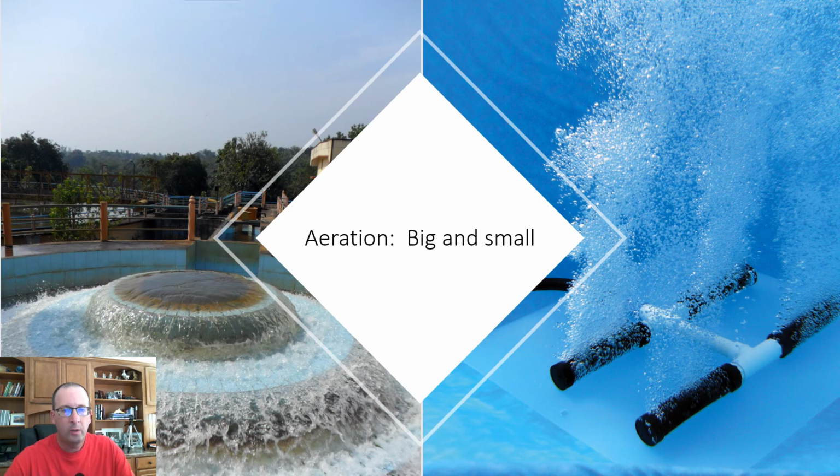So the next thing that we want to take a look at is aeration and also degassing. Basically, aeration is the idea that we're going to add some oxygen to the water and we're going to get rid of the CO2 when we go to degas. Now you guys already remember most likely that the oxygen in ponds and in tanks is less available for fish than it would be for animals that live on land.